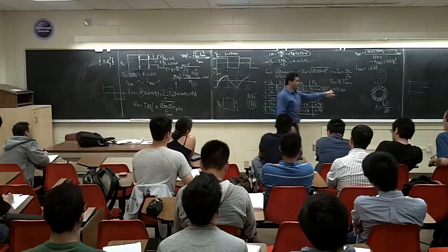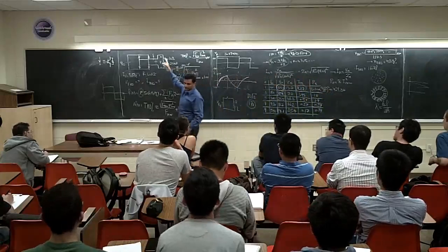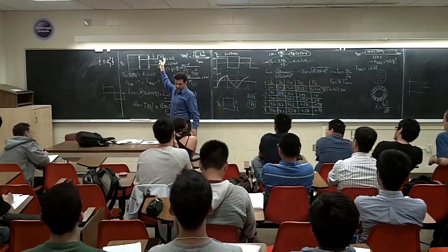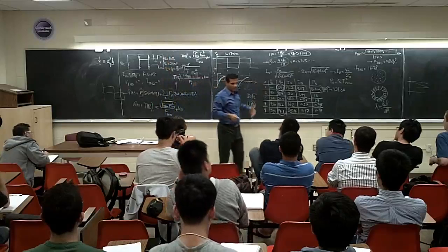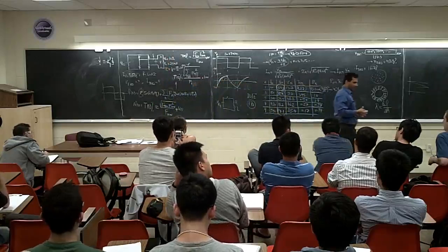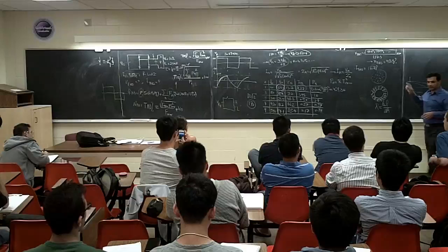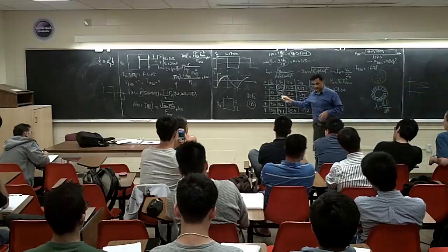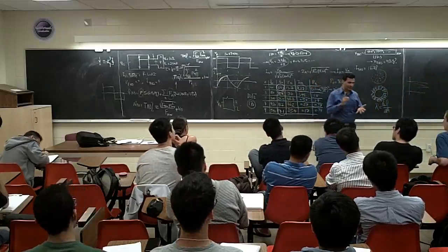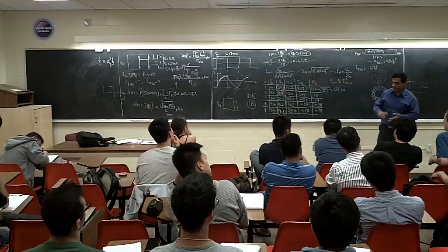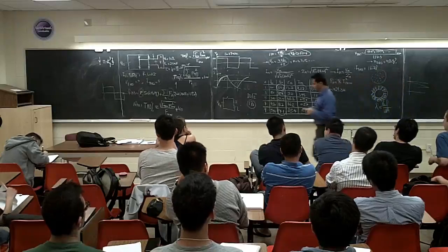How much was the output power here? 430 watts, right? If I have the same fundamental current here, how much power am I going to have? The same power. It's going to be R times this current to the power of 2. Basically, it's trying to compare these two examples. If I want the same output power and get rid of the third harmonics, who designed your system? Let's calculate it again: the THD of the voltage, the THD of the current, how much DC bus I need, how much battery I need. So this is the question.